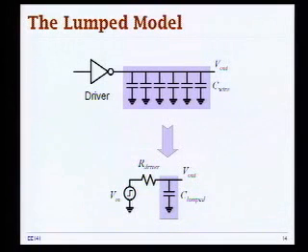So we first started with a simple lumped capacitance model where we say, well, let's assume that our gates are really slow and that the equivalent resistance of a wire is really not that big of a deal from the delay and performance standpoint. So we can then just simply approximate a wire as just one lumped capacitance that is driven with some equivalent resistance.